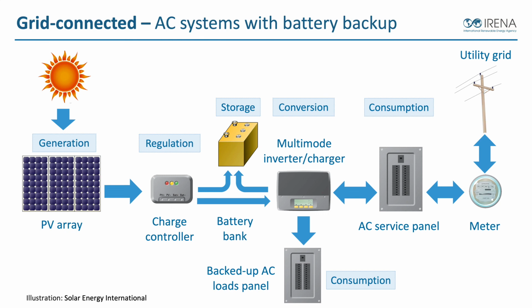Now, people often ask, can I back up an air conditioner? Yes, of course you can. You can back up as many as you want. It's just going to affect the price and the sizing of the system. Maybe if you have multiple air conditioners, you back up one in a common area and leave the other air conditioners in the main service panel that's not going to be backed up.